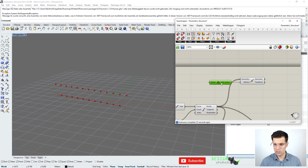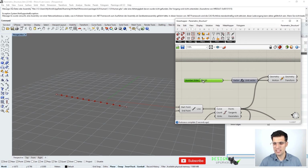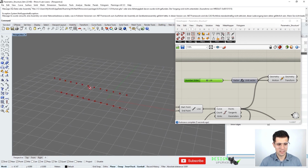So in order to do that, I'm just going to define a new slider, which is going to go between 0 and 5 meters. And of course, this is going to be a real number, not just an integer. So we connect the slider with our vector component here, and now we don't see anything because the slider is 0, but if we update this value, we can see how we are moving these points in the vertical direction.